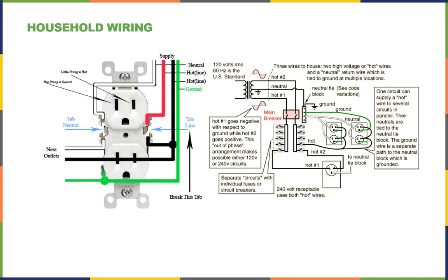Voila! It goes around the loop from ground to your power supply, back to the water pipe, back to the ground. Yeah. Hold up. That's really interesting because when I was in Zambia, our sink would always shock me. Like, if I touched it a certain way, it would shock me. You might have been in a situation like that. I don't know, but that's a bad way of doing it, because if you have it connected to the sink and the sink is not well connected to the earth, and you touch it, you get shocked.